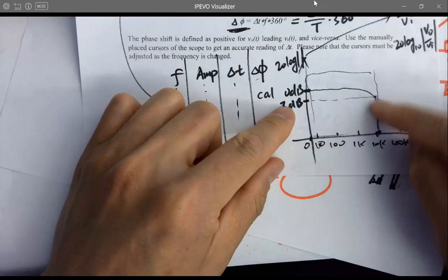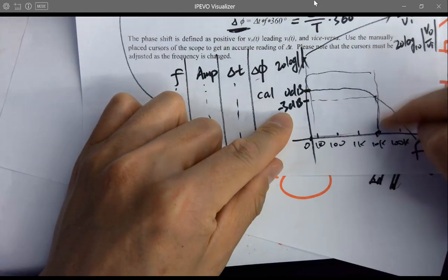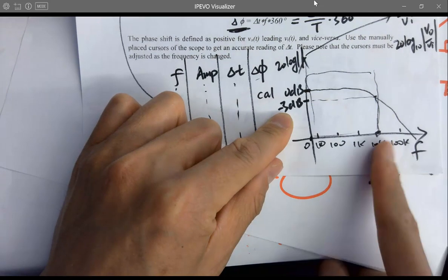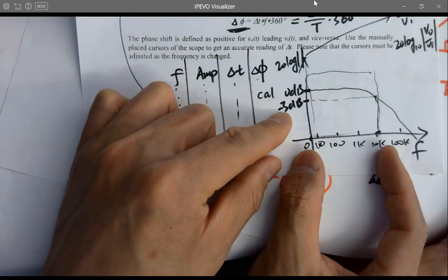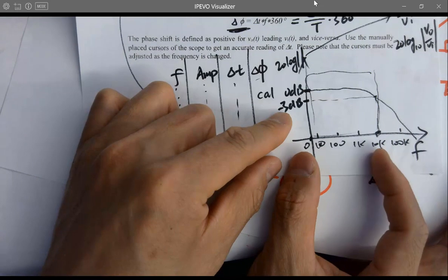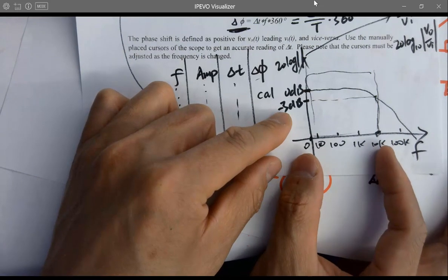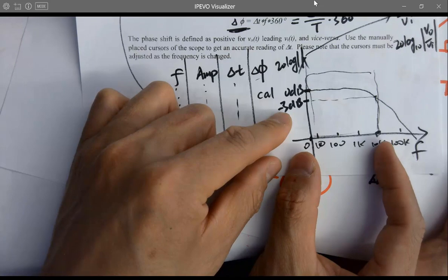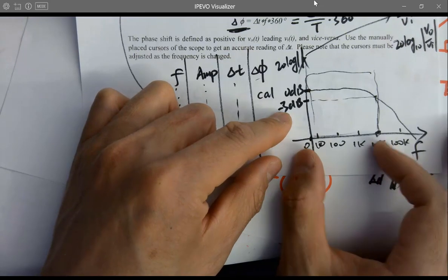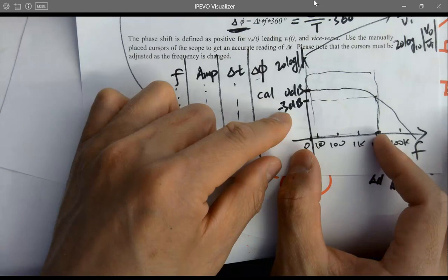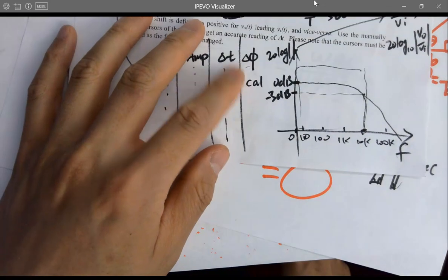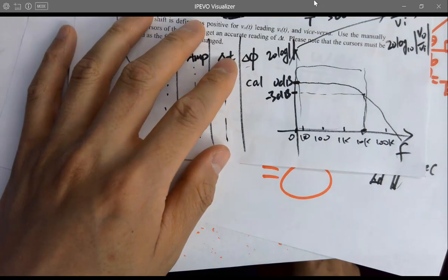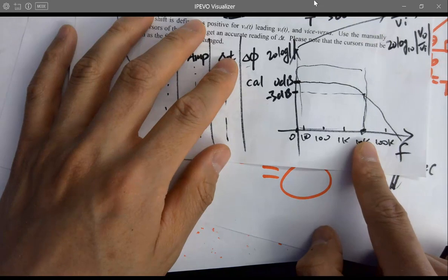For the low pass filter, if you find out the 3 dB frequency, you get the attenuation first, locate it on the curve and find out the X value of it, which is a frequency. So that's the bandwidth of the circuit, or you can say that's the pass band of the filter. Any frequency higher than the bandwidth will be attenuated, it won't pass the filter. I've heard about the bandwidth term a lot of times, right? So here it comes. That's the bandwidth of the circuit, of the filter. Cutoff frequency, which is here. Okay?